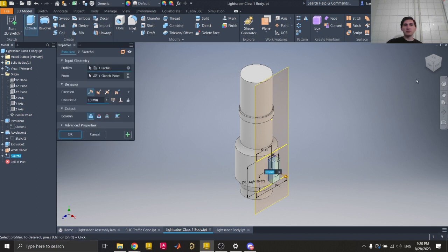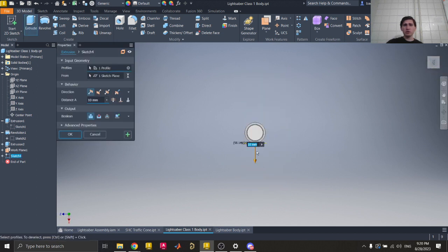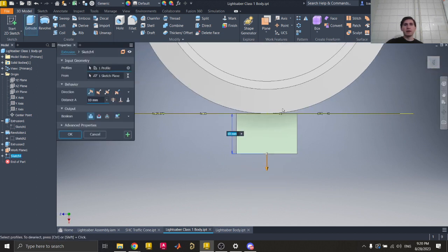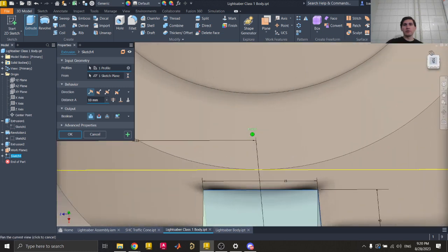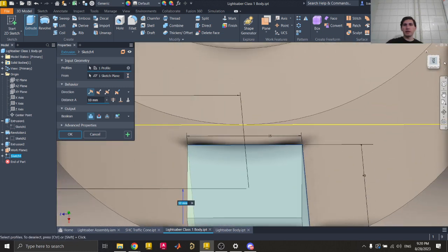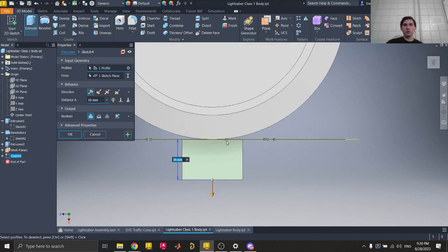So back to this extrusion bit. If I extrude on this one side, there's a little bit of that kind of an ugly area where it isn't fully connecting. If you try to 3D print this, it will 3D print these two parts or these two solid sections as two different parts, or it'll just print off in the middle of open space and it'll just fall. So we need to actually get this connected properly.